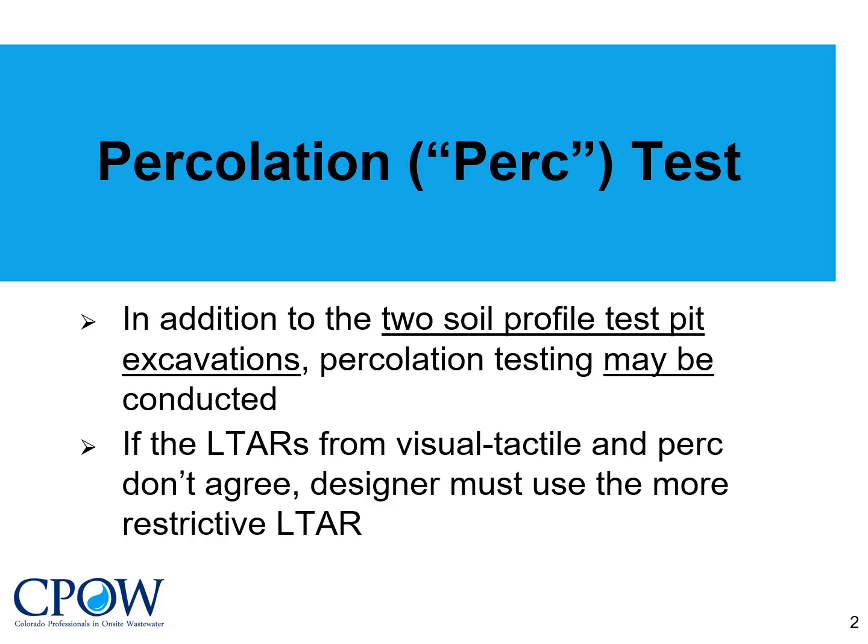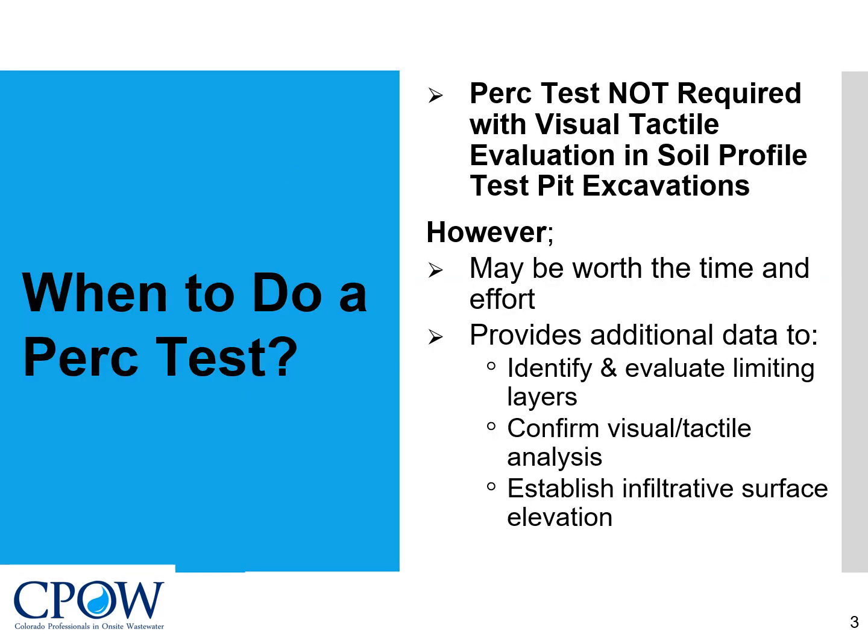Percolation testing may also be conducted. If the long-term acceptance rates from the visual tactile analysis and the percolation tests don't agree, the designer must use the more restrictive LTAR. Percolation tests are not required when conducting a visual tactile evaluation in soil profile test pits. However, it may be worth the time and effort.